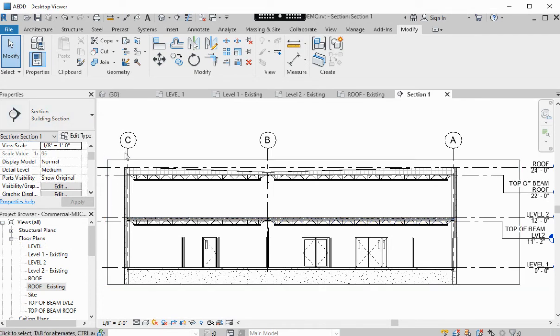Also, these column grids come in handy for any kind of project where you have to locate things in a precise location and you are ending up repeating a pattern. So that sums up what you're doing with the existing structural. And then what you're going to do is move on to the next module and add the curtain wall systems as the next step that are also existing conditions.